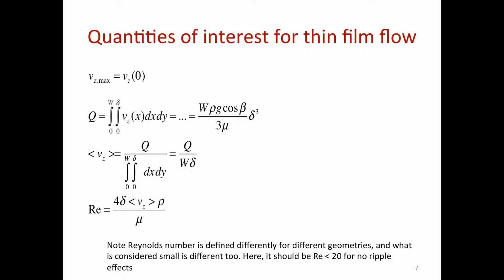Once they're similar, conceptually Reynolds number is some velocity that is characteristic for the flow, times rho, which is the density of the fluid, times some length that is characteristic for the flow, divided by viscosity. Which particular velocity am I going to take, V max or V average? That's up to the research community to decide, and typically there is some historical velocity that is taken. In this particular case, for the thin slit, it's this average velocity. Which particular length to take is also up for discussion, and historically, different types of lengths are taken for different geometries. If I have a bowl, I'm most likely going to go for the diameter of that bowl, right? But somebody could go with the radius.